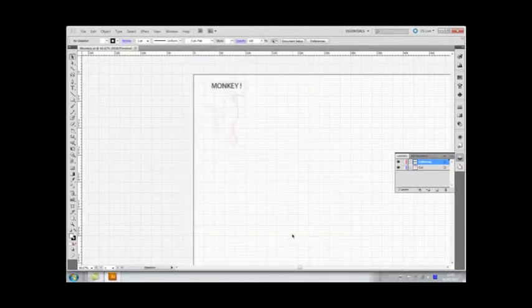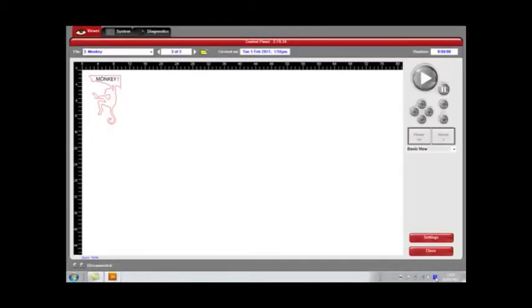Right, so now that we've done that, we're ready to go into what's called the Universal Laser Systems program. So that's down here. So here we got on our control panel, we can see it. It'll be red on the Lasercutter computer. So now if we click on that, we can see that the file has been successfully transferred across. If it doesn't appear like it does on the Illustrator file, then you've got a problem with your file, and basically certain things might need to be changed. So please get the help of either Jake or John to help you with that.